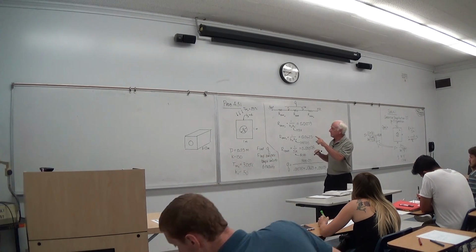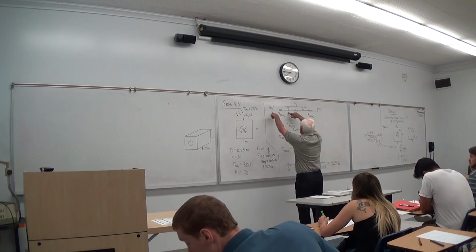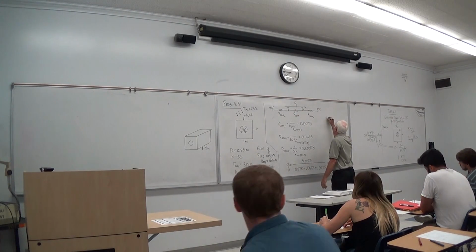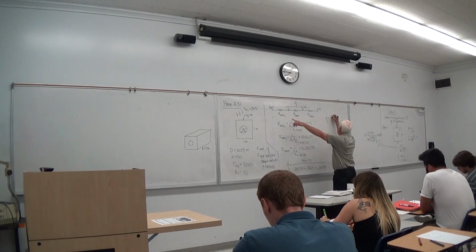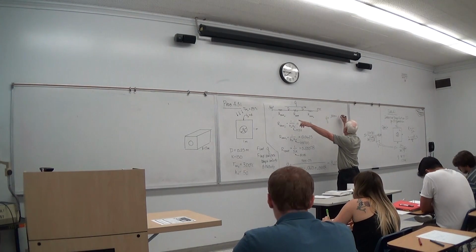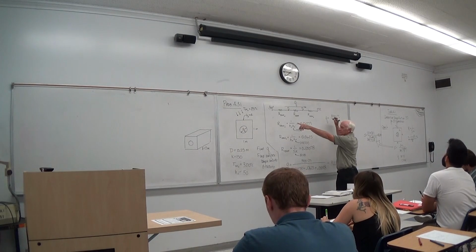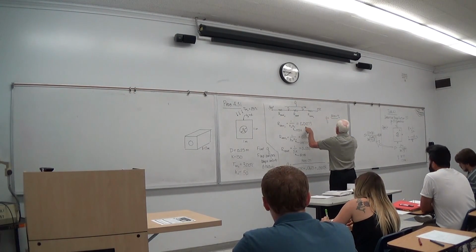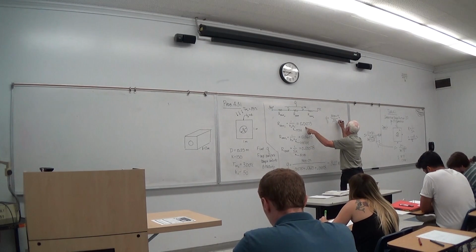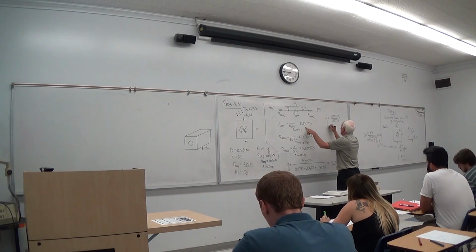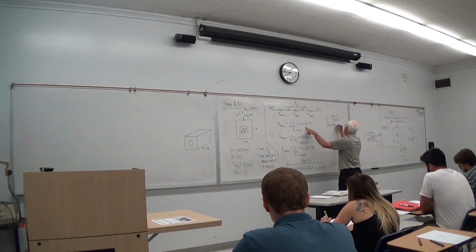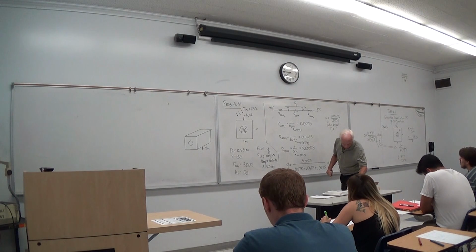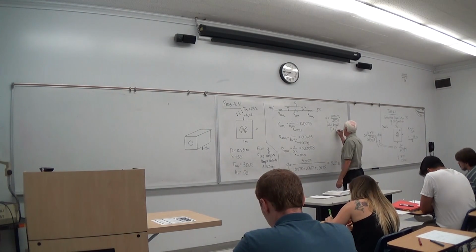Like the heat transfer equation from 300 to TI. Q equals hot temperature minus cold temperature divided by the resistances between those two temperatures, or convection inside. Solve to get TI equal 254 degrees C.